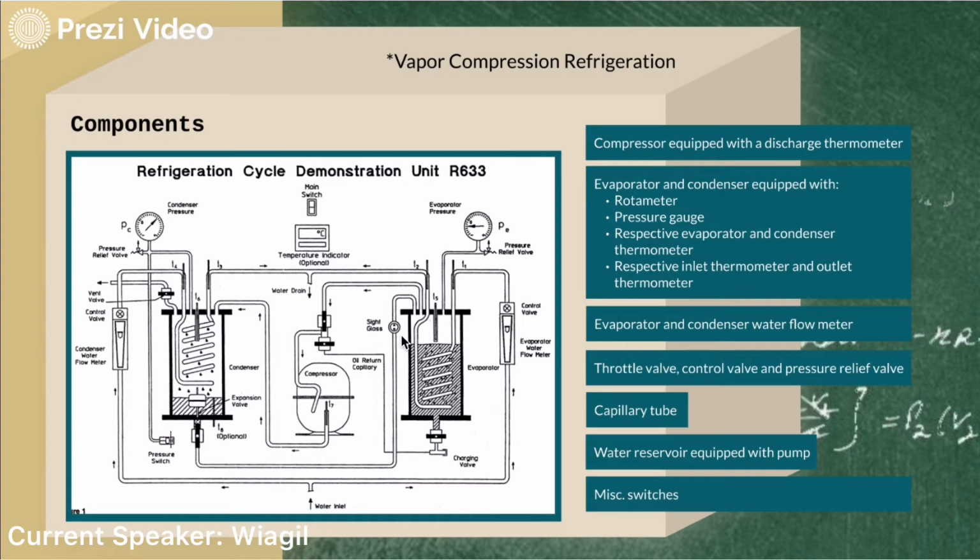This reduction of temperature is accompanied by the formation of vapor bubbles, and this liquid-vapor mixture can be observed through the sight glass. So on entering the evaporator, the low-pressure liquid and vapor mixture separate. The liquid will enter into the refrigerant pool for evaporation, while the vapor will mix with the vapor produced by the boiling action of the water coils. See, evaporation occurs here due to the reduction of pressure as a result of the vapor being drawn by the compressor. And when vapor is drawn by the compressor, it causes the refrigerant pool to boil at a lower temperature. The vapor mixture accumulated from boiling then returns to the compressor to repeat the cycle.